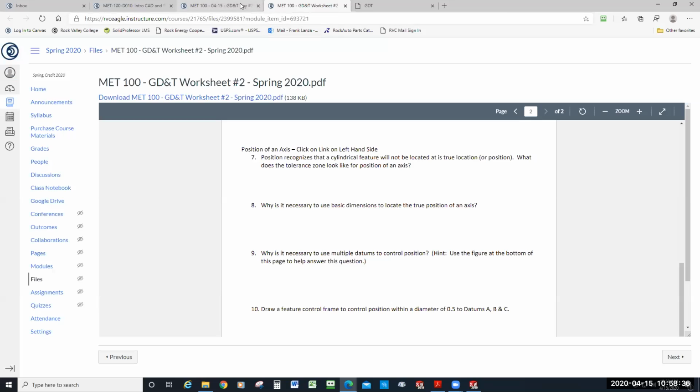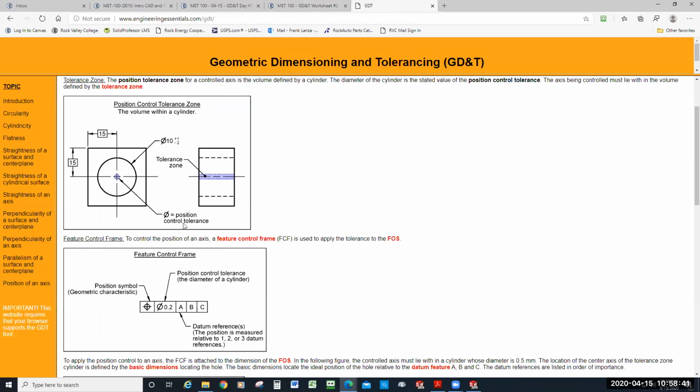So a second way of looking at it would be if we didn't have these shown as basic dimensions, then the fact that they were whole numbers would automatically put a tolerance on the location or the variance of this dimension and this dimension, right? Because if we have nothing else telling us what that location is, this would revert back to the tolerance block in the title block. So now you'd have some conflict.